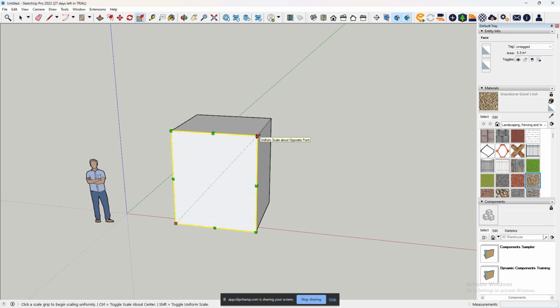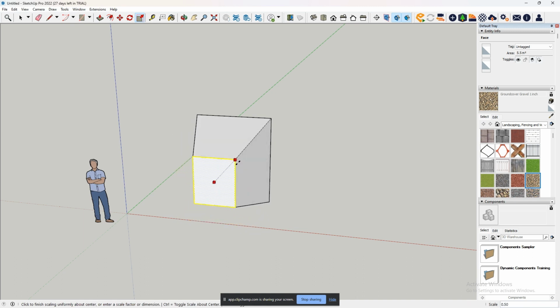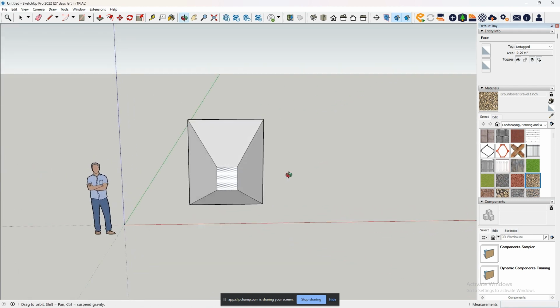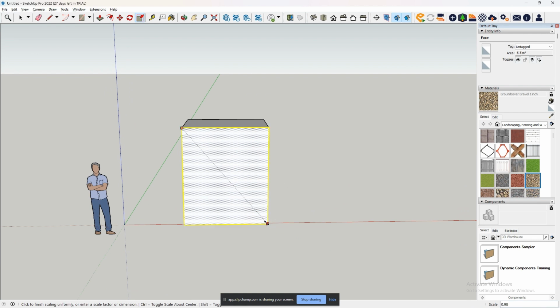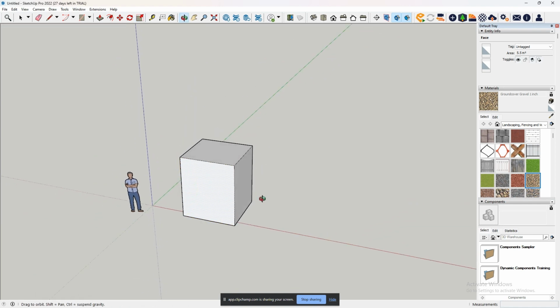If you want to taper an object, you would highlight this one face here, holding the shift key, my mistake, I believe it's the control key, yep, the control key. It's going to taper it just like that, and it should keep it all within the same proportions as well. Just like so. The shift key allows you to move it in whatever ratio you want. Without the shift key, it will stay within that one ratio. And that's with one face.